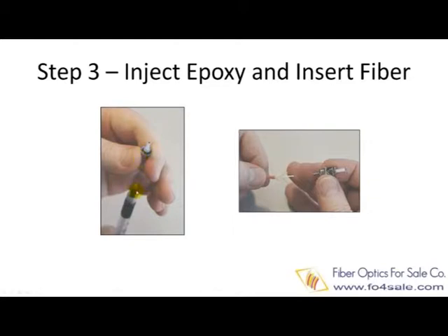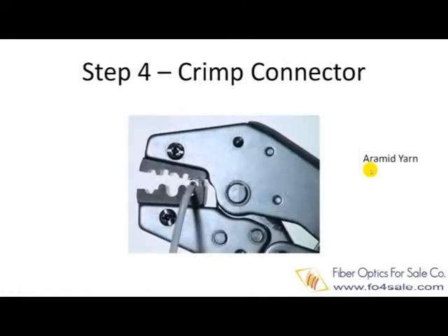Now, as you may know, one of the most time-consuming steps in a conventional fiber optic connector assembly is the polishing of the end of the terminated fiber that pokes through the tip of the fiber connector. The style of pre-terminated connector has a built-in pre-polished fiber stub at the tip of the connector.